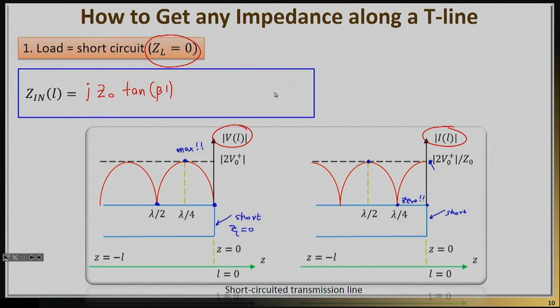So, in other words, just by moving a quarter wavelength away, you go from having a short circuit to having an open circuit with a maximum voltage and a 0 current. So this idea of changing impedances between short and open, or open to short, in a short transmission line is very, very powerful. And again, it only takes a quarter of a wavelength to make that happen.